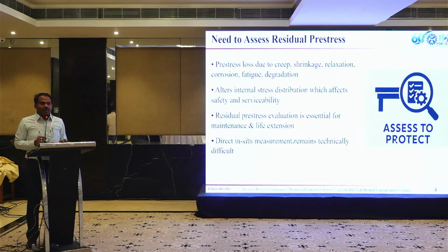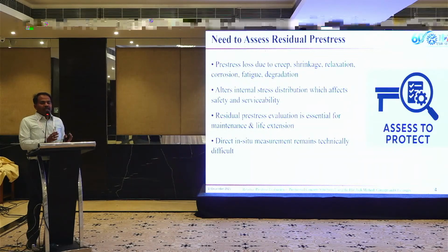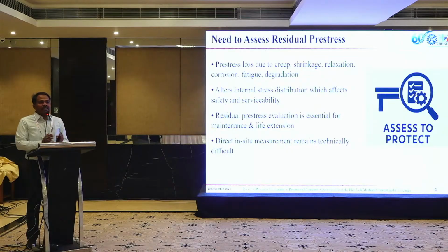Then, why do we need to measure the residual pre-stress? Why do we have to evaluate the loss? To ensure whether the structure is performing its function or not. If the pre-stress is reduced, then it leads to more deformation, and it leads to tensile stresses.